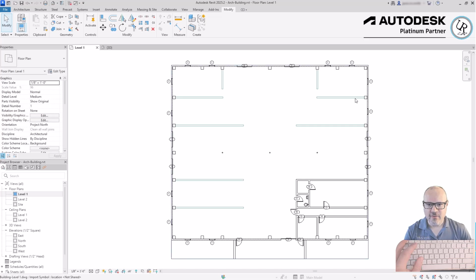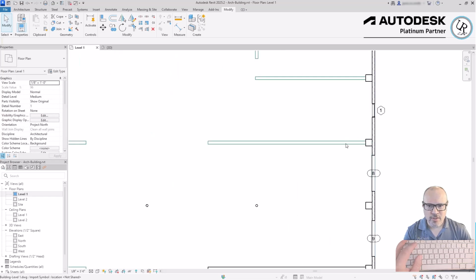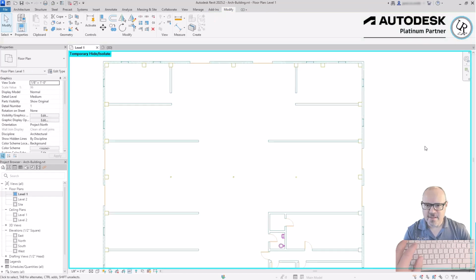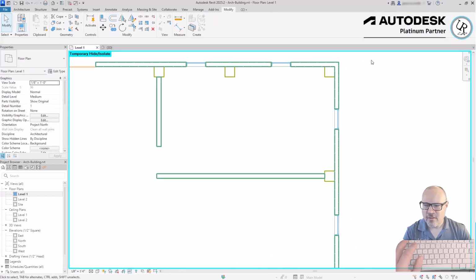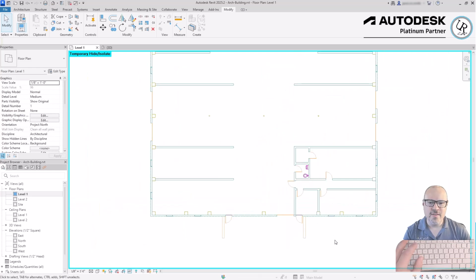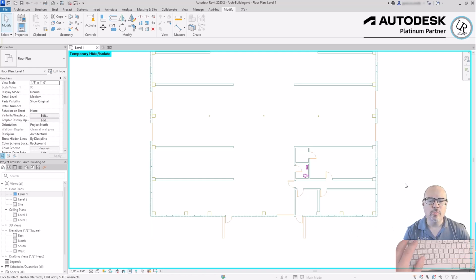As I look at this CAD file link connection, I can clearly see that there are some interior walls here that were not part of my own Revit model currently. If I choose to select that CAD file and isolate it temporarily, I can see the CAD file and its relative colors shown here. So all of this information comes from that AutoCAD file. Whether this is a renovation of a building that you have an AutoCAD file from, or you're working with a consultant that is using AutoCAD, you can still bring their content in for use in your document.